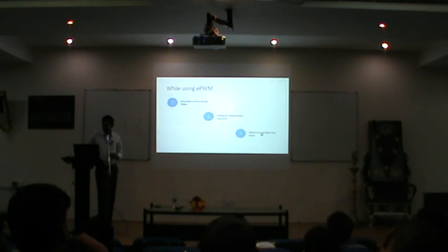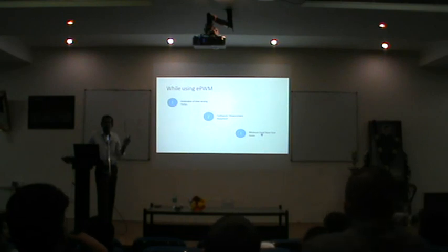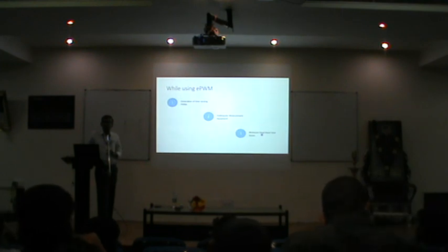This also is another thing. The dead time which can be generated to its minimum extent by any given PWM module for a particular clock frequency is fixed. I am talking about the minimum value, not the instantaneous value. That will be fixed.